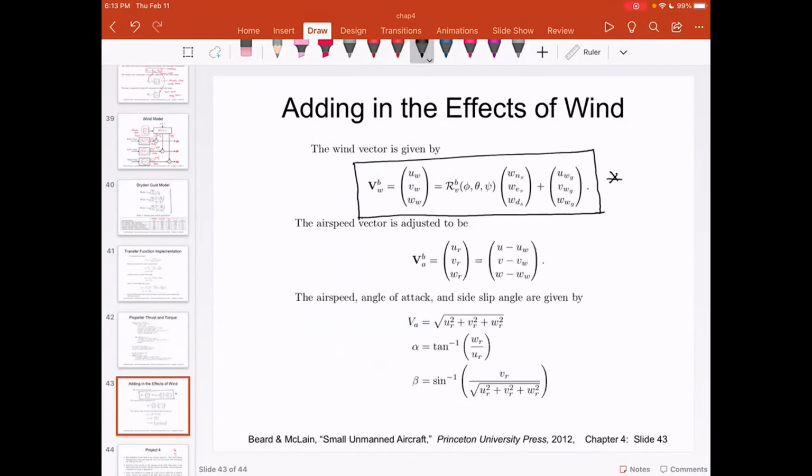So no matter whether you use the transfer function approach or maybe the MATLAB Simulink approach, the idea is finally we want the wind, comprising the steady state component and the transient component, in the body frame. So once we have the wind vector, we can find out the airspeed. This can be used to find airspeed, as airspeed is the velocity u v w minus the wind speed.